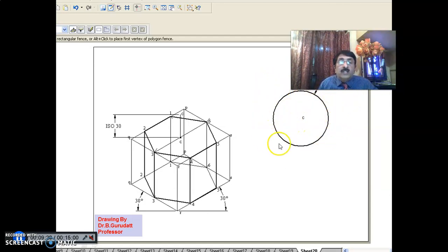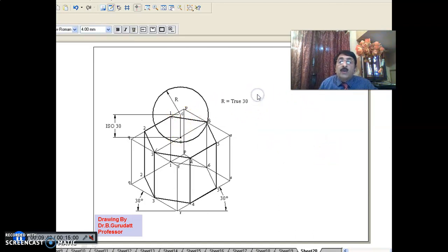Don't reduce this because it's a sphere. Then move this with respect to this C so that this C coincides with this C. Okay, that is, don't copy, just move this with respect to this C and align it at the end of this, or fix it at C. Okay, now if you do this, the problem isometric projection is more or less over except the visibility.